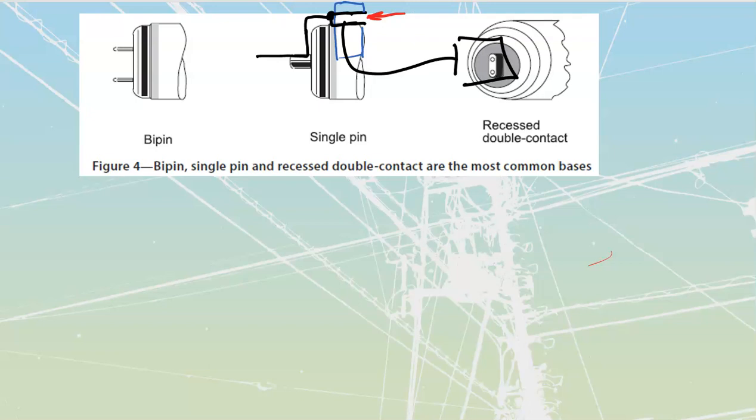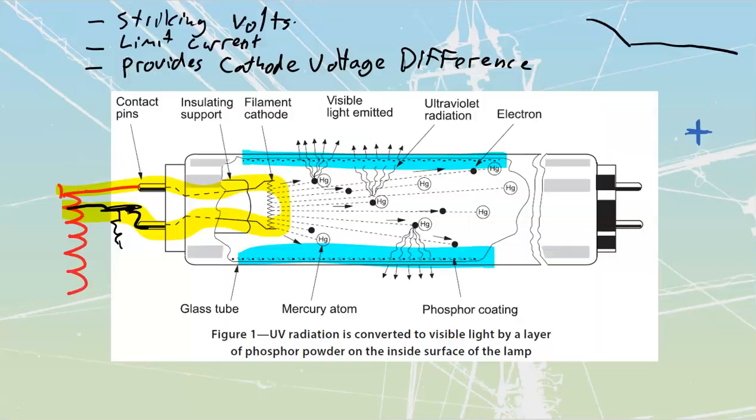These days, if you use electronic ballast, you don't have to worry about as much, because electronic ballasts operate at ridiculously high values of frequency. We're talking 20 kHz and above, which means that the electrons moving back and forth, rather than doing so 120 times a second, half in that direction, half in the other, are now doing that 20,000 times a second. We're actually changing direction 40,000 times a second. So it's a really, really rapid back and forth, back and forth, back and forth.